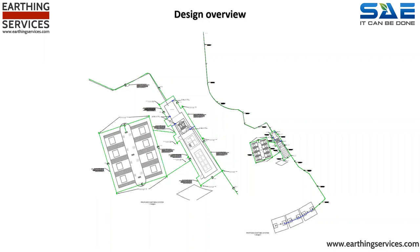The horizontal electrodes were 120mm square hard-drawn bare cables encapsulated within conductors and reinstated with native soil. This conductor needed to be installed at a depth of 1200mm to ensure it was placed within the lower resistivity layer that we would only have known was there due to the soil resistivity survey undertaken.